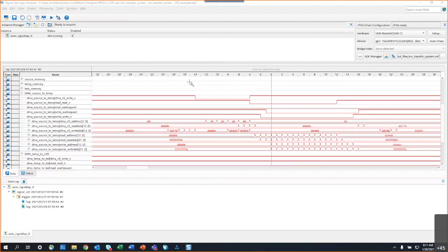Yeah, I'm not an expert on that, but SignalTap is fully scriptable for starting the logic analyzer and reading the results back. You can also, if you want to be able to parse text, choose one of the output options for SignalTap, which is to output a list file, an ASCII text file, instead of the graphical waveform. And you could parse that with a script if you want to analyze the output. So I don't know if that answers your question, but SignalTap is fully scriptable for normal operation.